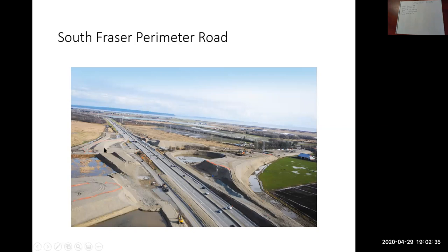For now, we'll assume they're embankment fills, just for simplicity's sake. In building road, the new finished surface is not necessarily at the same elevation as the existing surface, as we can see here. The height of this fill is probably 7 or 8 meters high. A lot of fill went in here in order to bring the road grade up high enough to get it across this highway.